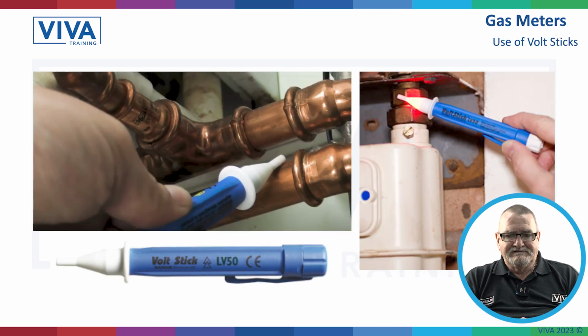So, volt sticks. The reason we'd use a volt stick, and the reason we're using a 50 volt stick, is that death has been recorded as low as 60 volts. So if we touch something and there's over 60 volts in it, we could be killed. That's why, if we're using a volt stick, companies like Northern Gas Network and Cadent, all their engineers will have